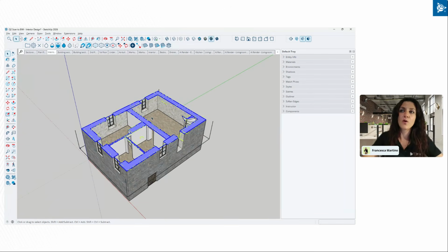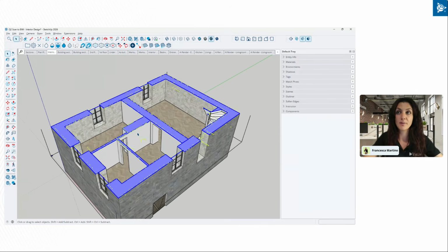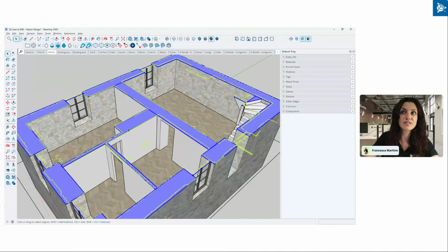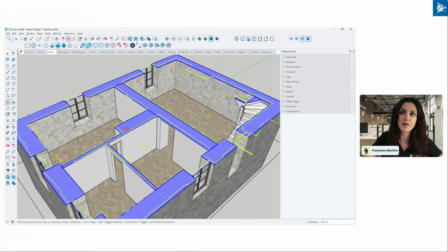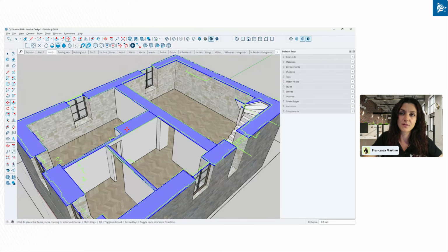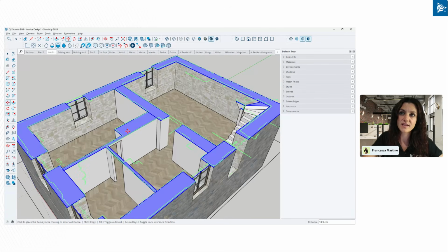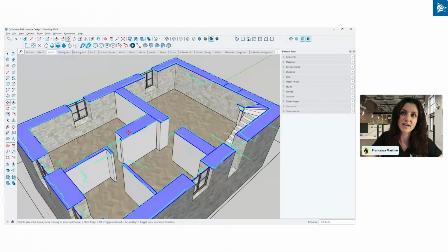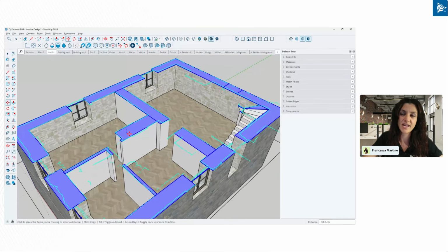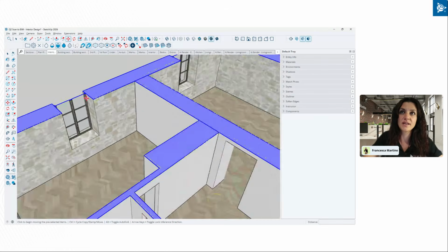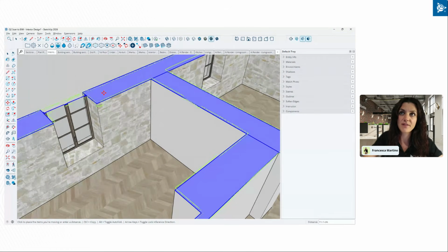Another important thing of using this technique of visualizing only the points that intersect my section cut is that I can use this as a way of verifying that whatever I actually built and whatever I model does correspond to reality. So if I slide down this section cut, we can see that the point cloud we visualize moves alongside the section cut. And so, for example, we can make sure that in the case of this window, everything corresponds.